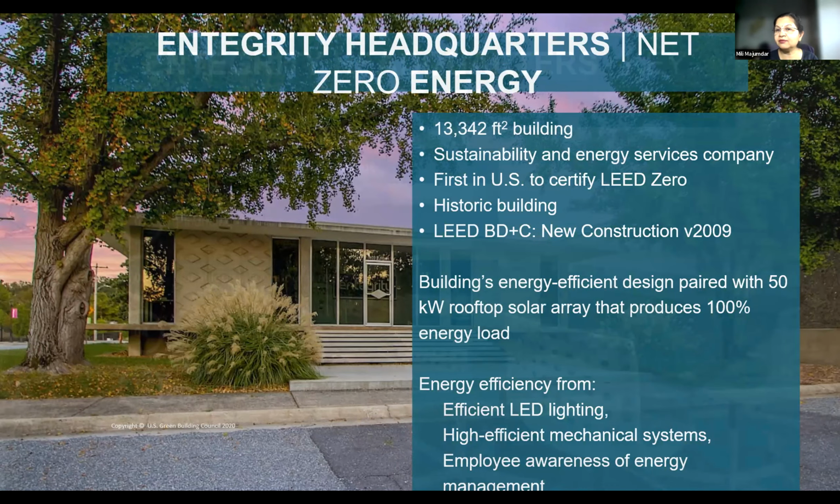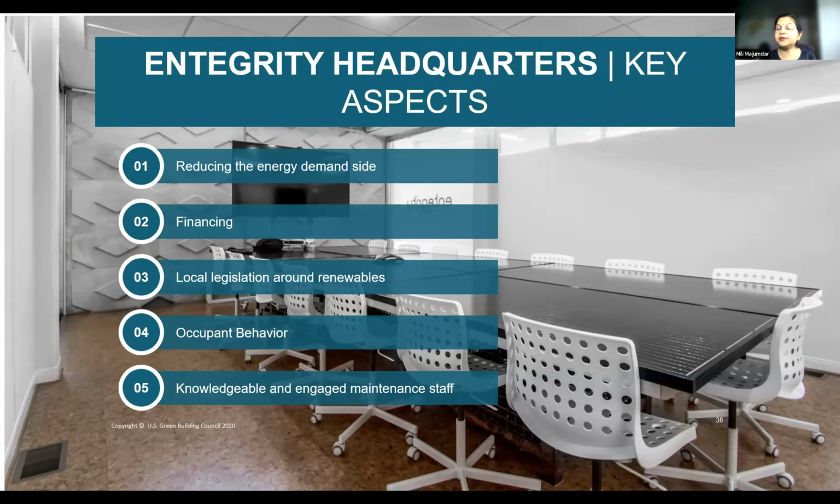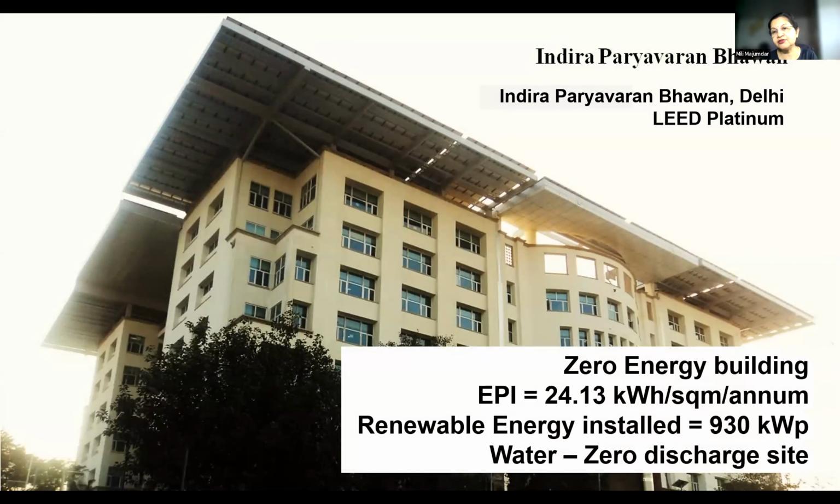And one of the important things which they mentioned is occupant behavior, that people inside the building, which is designed as net zero or energy efficient, have to be equally responsible to maintain it at net zero. Now, switching places, this is one of the first net zero buildings in India, which is the headquarters of the Ministry of Environment and Forest. Very well designed and net zero design. But unfortunately, I have walked the spaces inside the building and I have found that the occupants inside are not aware that it is designed as net zero. As a result, they have bypassed many of the technology options and not retained the energy efficiency features that were embedded initially in the design.